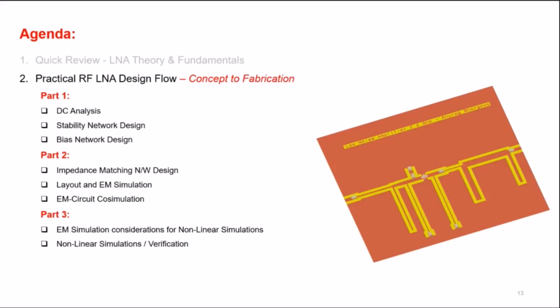And that's why you cannot do a lot of things on PCB that you can do in IC. In IC, if the first stage is using a feedback loop to achieve a flat gain bandwidth product or to increase the bandwidth, you can always compensate by doing a 3-stage LNA design, because the impact is very low, since you are only dealing with a few microns.